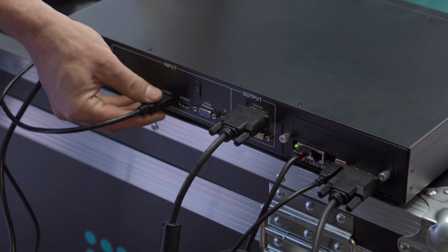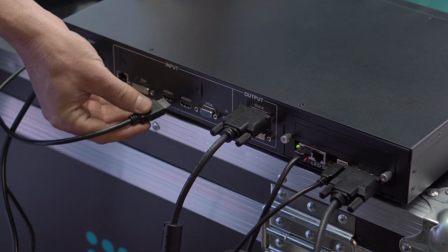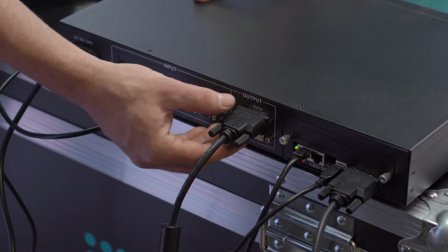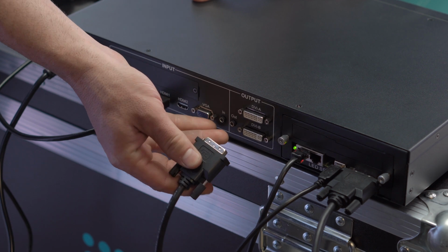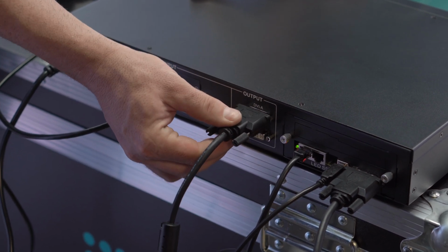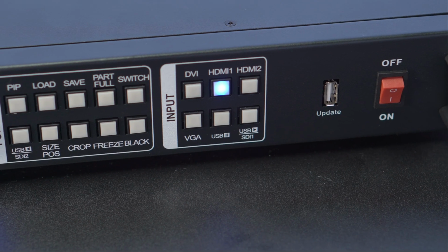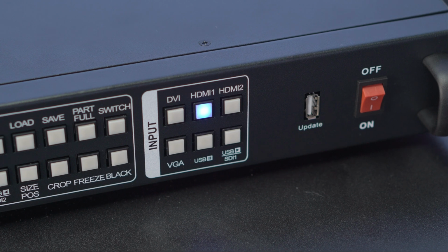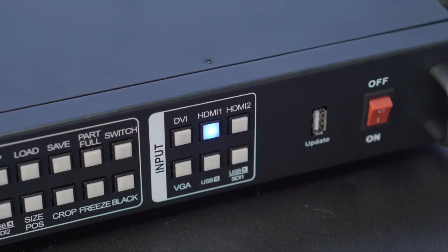No video source or not selected correctly. Ensure you have a video source connected to the processor via one of your processor's available HDMI, SDI, VGA, or DVI inputs. Then, verify on the front panel that the light corresponding to your video source input button displays a solid color. A flashing light button means that there is no successful connection established.